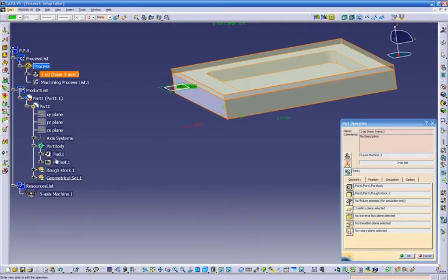If this is one part, let's keep separate folders, because once we do the verify, if, for example, on this level over here we have a couple of different parts, we're going to get an error when we try to run our simulation program. So it's very important that we keep everything in different folders and subfolders, and it's going to be very easy for us to click on them.